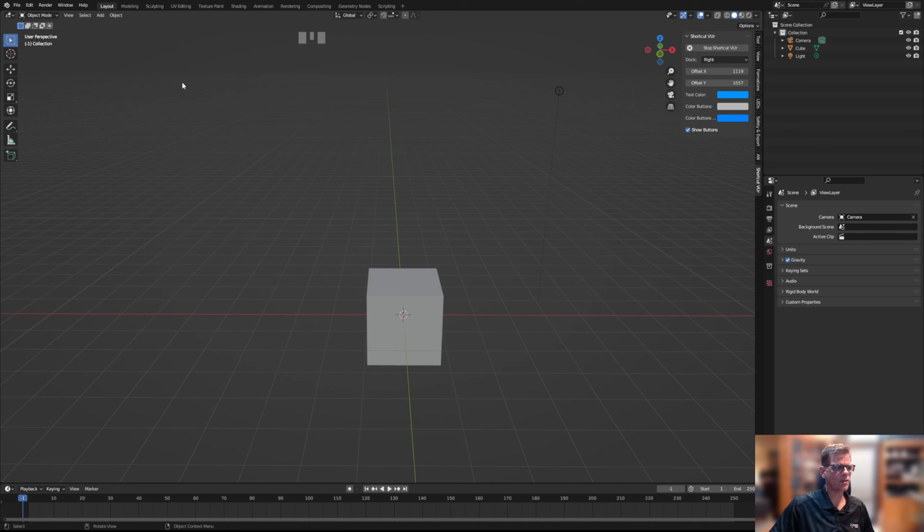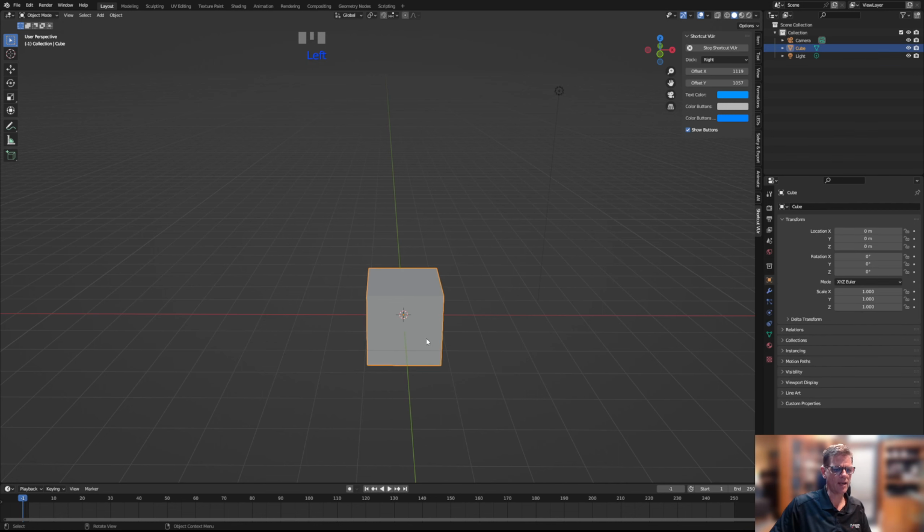It's important to understand which mode you're currently in. So we're currently in what's called the object mode. You can see that here in the upper left. To switch into the edit mode, which you're going to do a lot, you need to have an object selected. We now have the basic cube object selected, and hit tab, and that's then going to go into the edit mode. So just remember that you need to use the tab key frequently to go back and forth between the object mode and the edit mode.